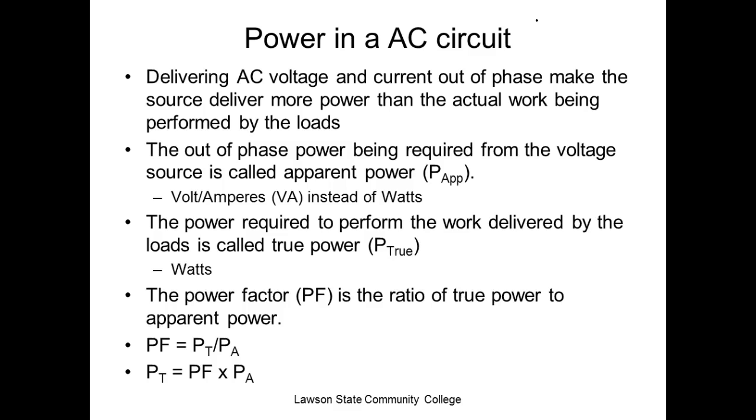So there's something called a power factor, and basically it's the true or real power divided by the apparent power. Now perfect would be 1, because that means your apparent power and your real power were exactly the same thing. That's what we're shooting for. Y'all understand that? Now, normally power factors are given in percentage.